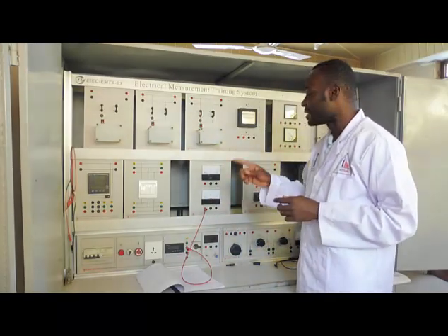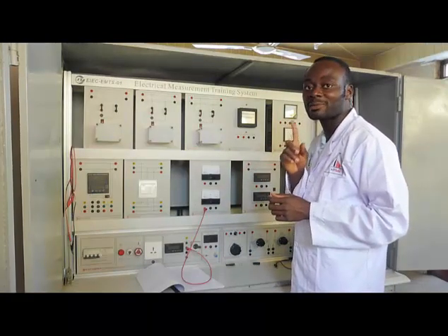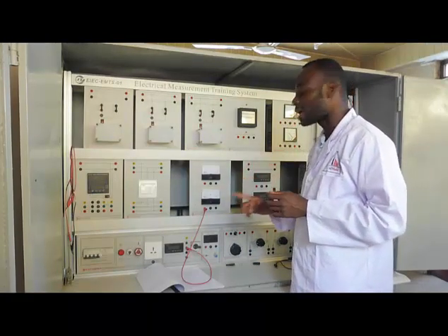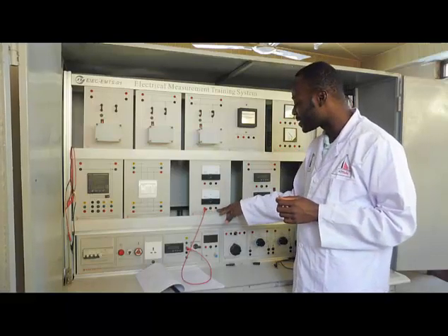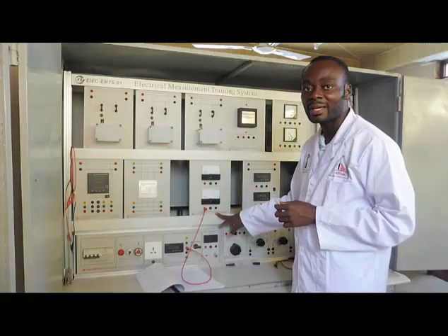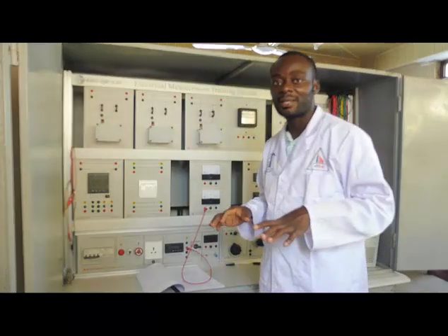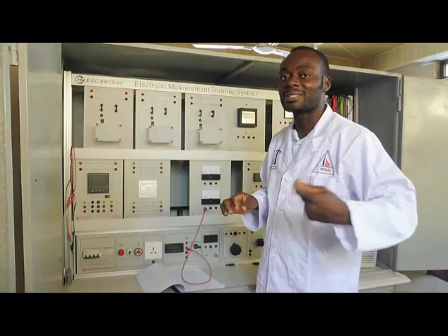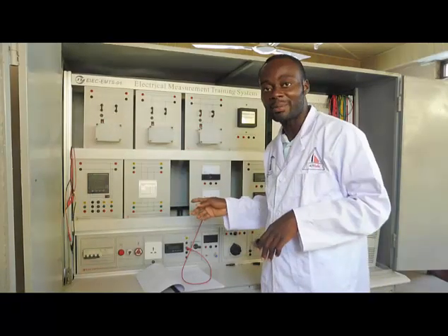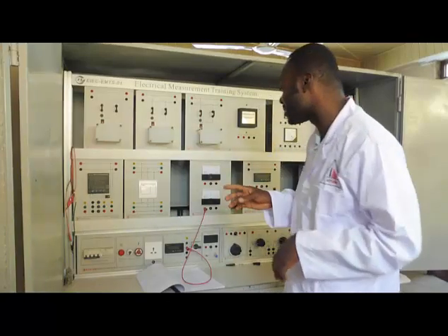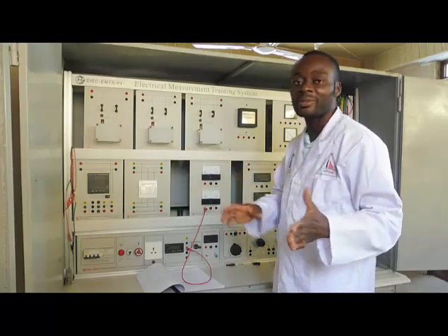So take note, the ammeter consists of only the live wire that is passing through. So you have the live input and live output. Although you see the phase as black, it's non-neutral. So take note, the ammeter is always connected in series. It's the live cable that is passing through the ammeter. There's no neutral connection with the ammeter. But the voltmeter is connected in parallel, so there's a live and neutral connection.